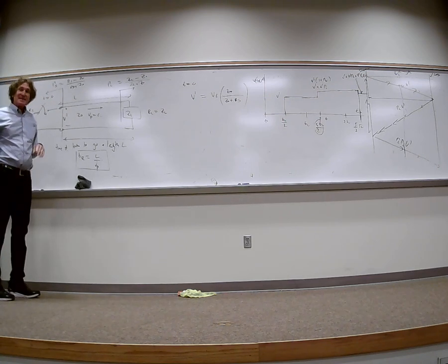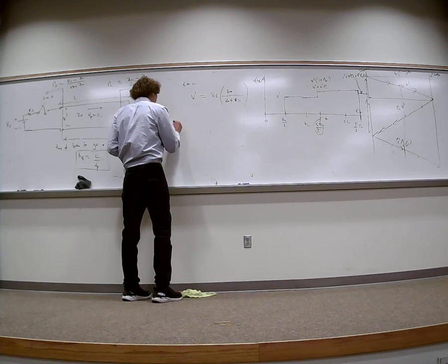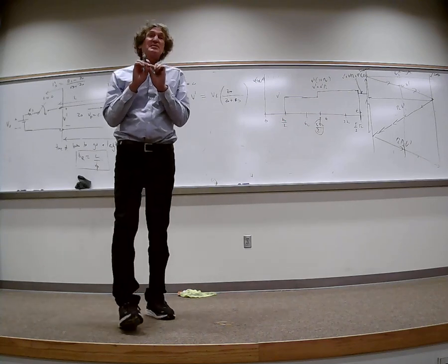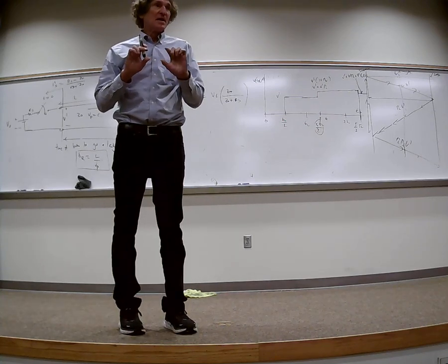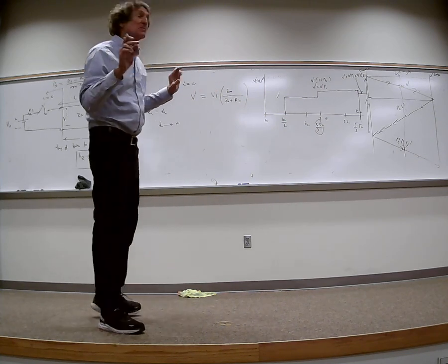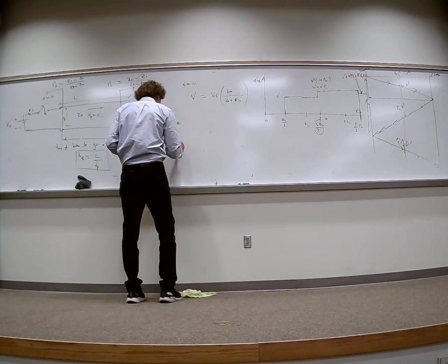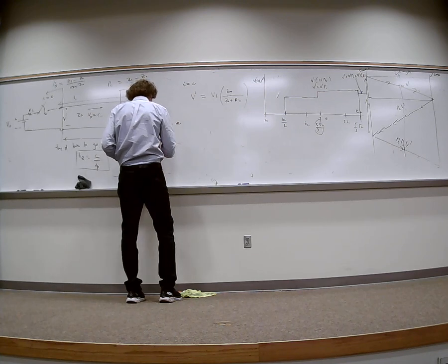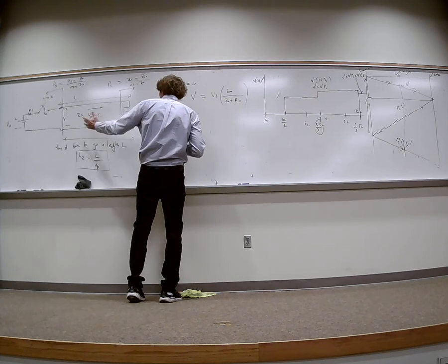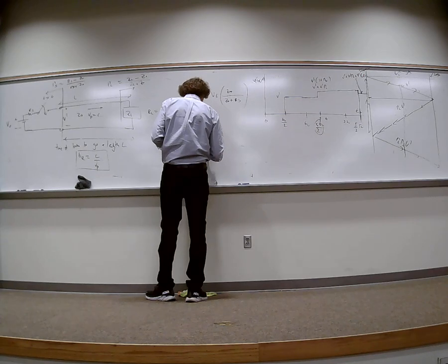you with me on this? As time goes to infinity, then the transmission line appears as just 2 pieces of metal, 2 conductors that are tied right to ZL, and you have RS. Do you all follow me? It becomes a simple DC circuit. As time goes to infinity, your circuit looks like this. You're going to have the same value of V0 here, and you're going to have RS. And now you just remove that transmission line, and here's going to be RL or ZL.